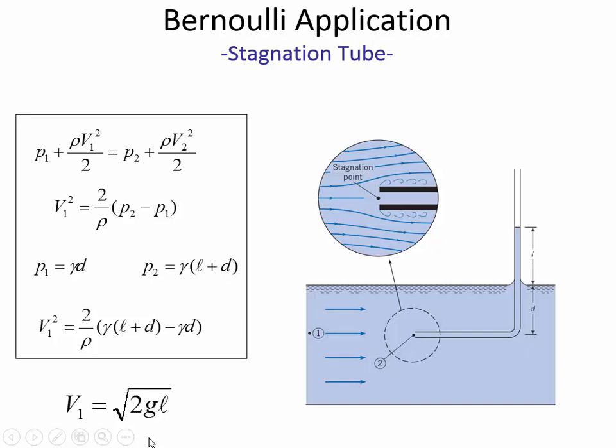So that's a pretty easy way to measure flow, if you're measuring a fluid that is inviscid, incompressible, and conditions are steady, and you're measuring it along a streamline. So along a streamline, that's going to be true here. Steady flow, as long as the flow rate isn't changing in the very short term between when you are taking your measurements, then that's valid.